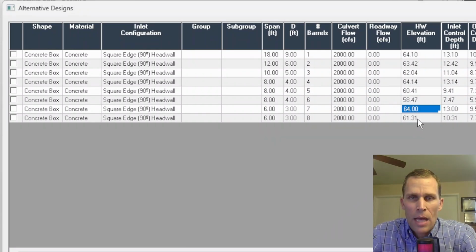That's good to see. As for doing the width check, remember we have 60 feet total width. That's another reason to use the fewest number of barrels. We're more likely to satisfy that constraint. So 3 times 10 is 30 feet. That's certainly less than 60. And then next was 4 times 8, that's 32. That's certainly less than 60. And finally, 7 times 6 is 42. More than the others, but definitely less than 60.